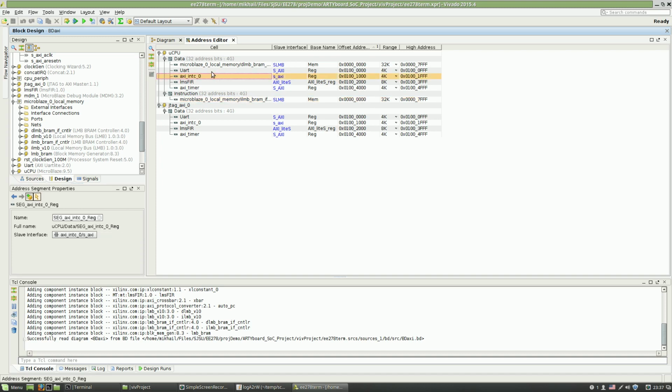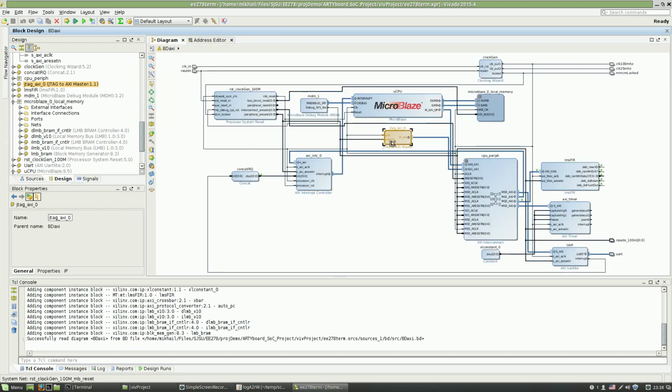As you can see, most of the IP blocks use a 4 kilobyte allocated address space, which is the minimum you can do. For the LMS filter, I'm using 8 kilobytes because the top 4 is the output buffer as a single block RAM. The JTAG bridge has access to the peripherals, as you can see. This sums up the SoC system.